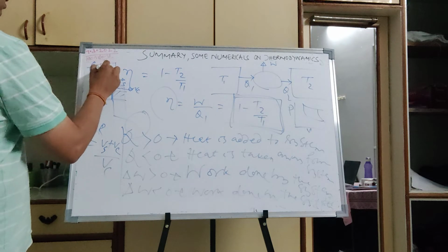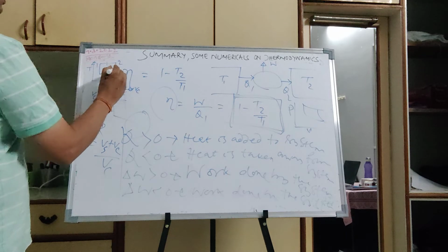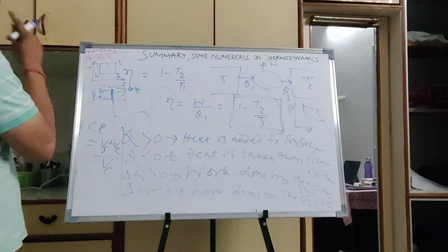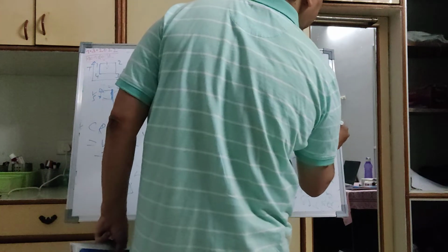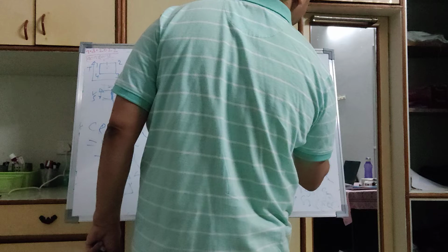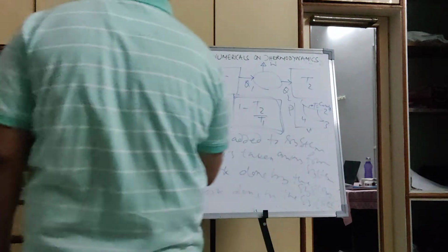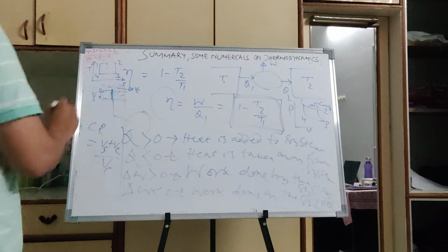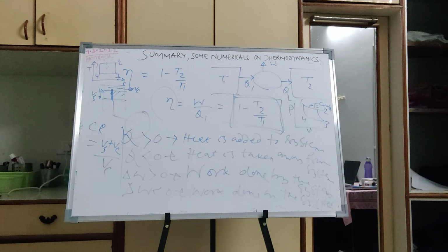So you are giving like that. This is the first to second. Okay, this is second to third. This is third to fourth. So you can see, from 1 to 2, 1, 2, 3, 4. So 1 to 2, temperature remains constant, right? So if temperature remains constant, this will become a horizontal line. And in an adiabatic process, S remains constant.